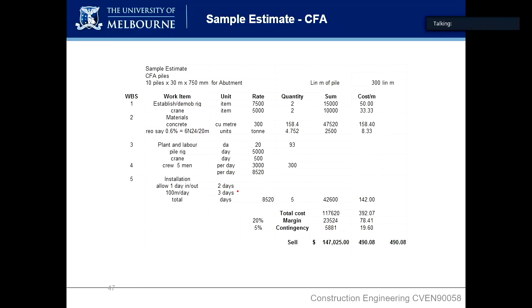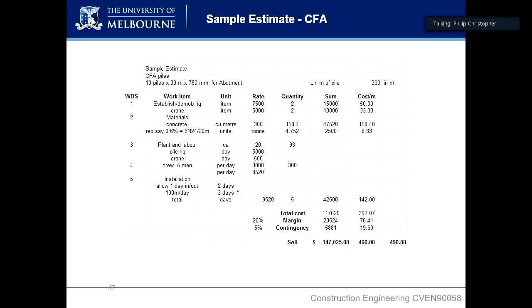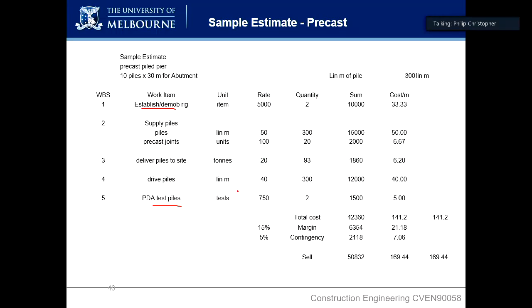Is that common? It's a good question. I don't have a definitive answer, but I can give you a guess as to why I think it's changed. Driving a precast pile in the ground is not exactly a sophisticated setup. It's basically a cable and a hoist that hoists up a big weight and drops it on top of the pile, and you just keep dropping that weight on until the pile is deep enough in the ground. It's not a very expensive piece of equipment or machinery, so there are a lot of contractors out there that can tackle a job like that.